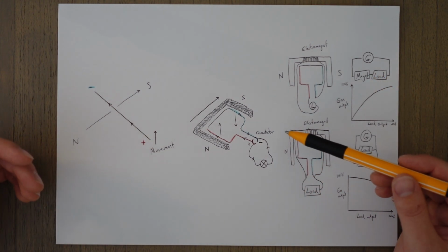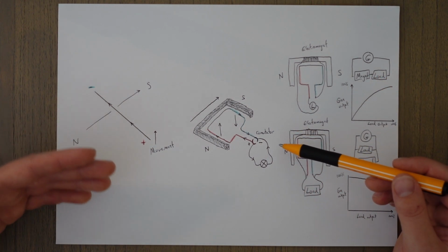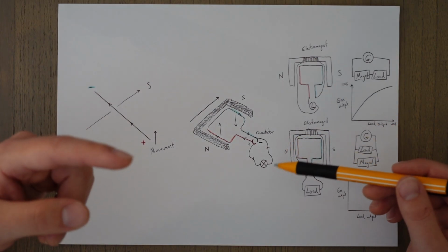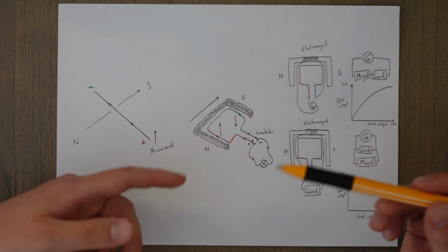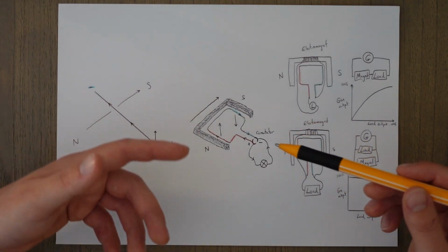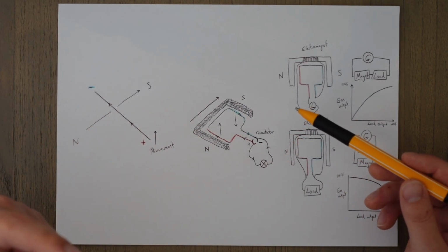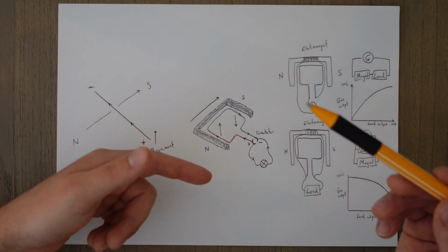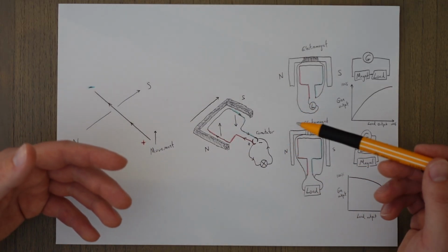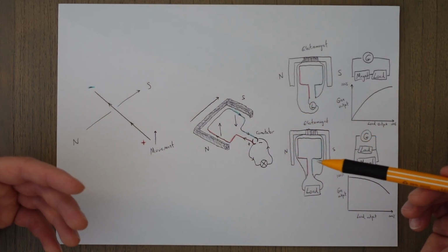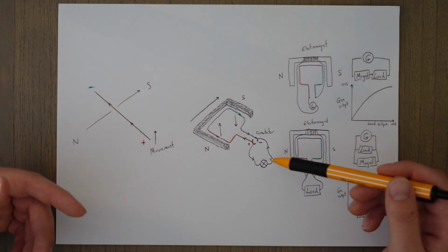The output current is controlled by a commutator. Remember how it controlled the switching of the current between each leg of the loop in a motor? Well, now it does the same thing. It basically ensures that the current output switches from leg to leg of the loop, and it keeps the current flowing in the same direction once it reaches the output circuit.